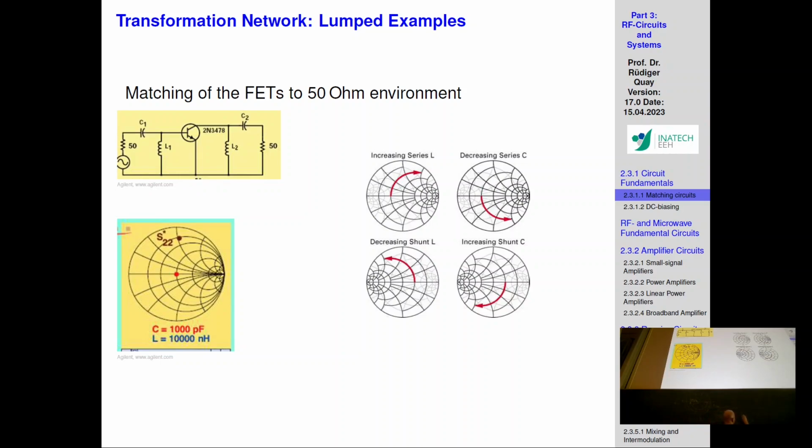Because this thing has its own gate source and drain source. And you don't know how this will change with temperature, how much the drain current will change. You don't want fluctuations here. If the voltage drops here and the current increases here, and the voltage doesn't change here, you don't want the current to increase because your device might get damaged. So beforehand, you have to apply a decoupling capacitor.